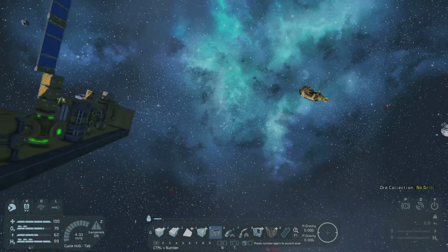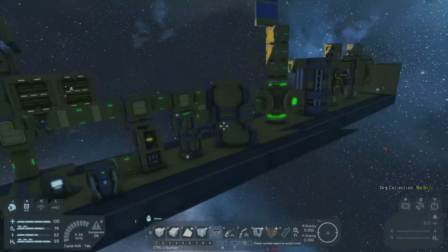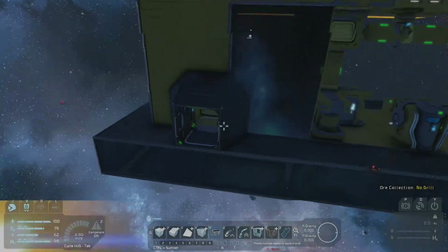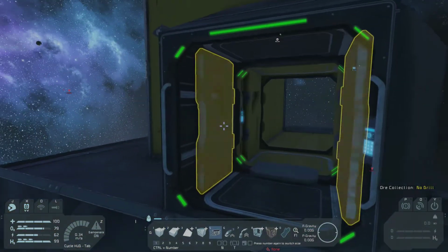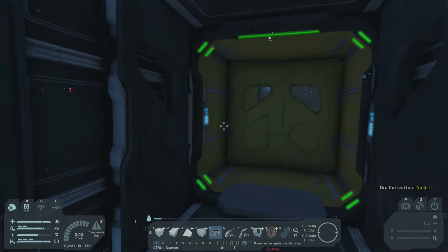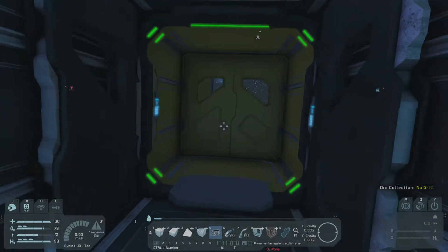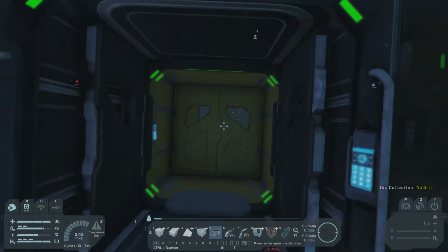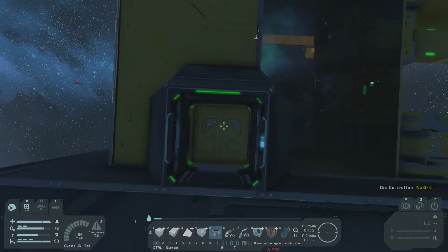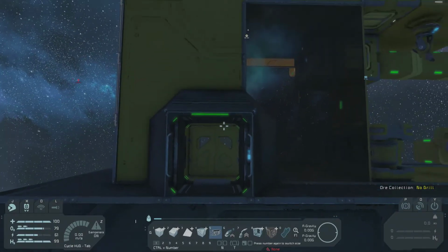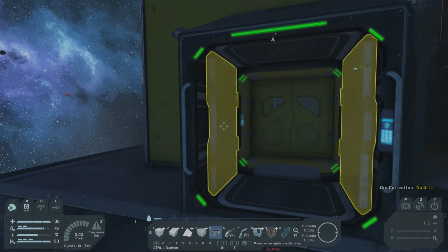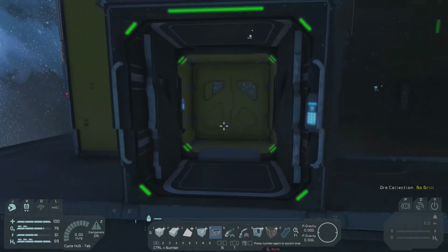So some base thoughts. When you have your containment area, you want to build an airlock. And what I mean by that is an outer door and an inner door. The reason for that is you'll only have one door open at a time. So if I'm coming in, then the inner door is what's sealing the environment inside. Obviously I don't want all the pressurization, the air, to come explosively out. So I will open the outer door, which will only exhaust the air in my airlock.